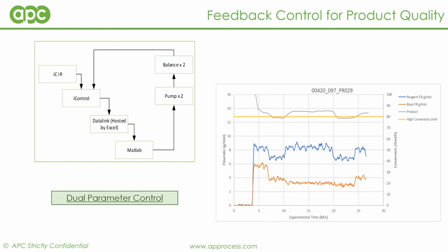One of the major advantages of decoupling the pumps and the balances was that although MATLAB was changing the internal setting of the flow rate, which was determined by the algorithm for the feedback control loop, we actually had a live check of whether this internal set point on the pump was being initiated correctly, and this was done by having the balance data feeding into iControl.